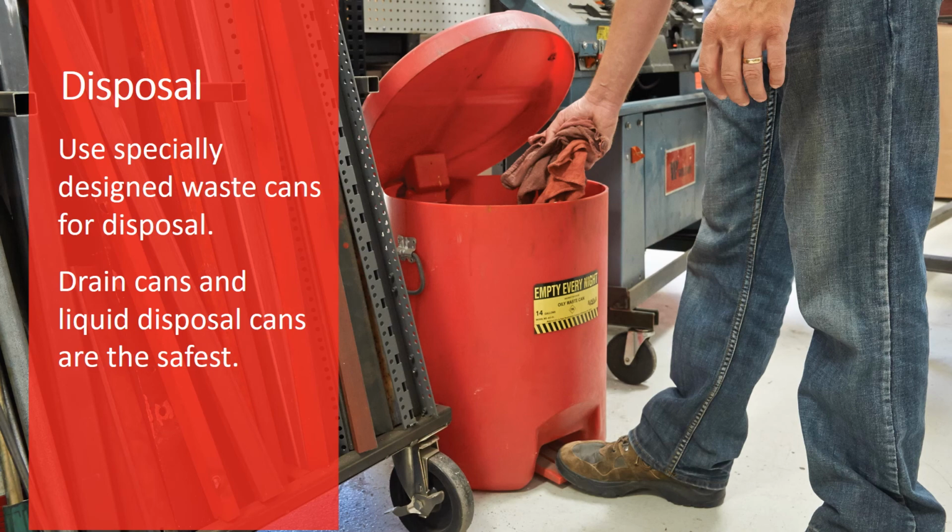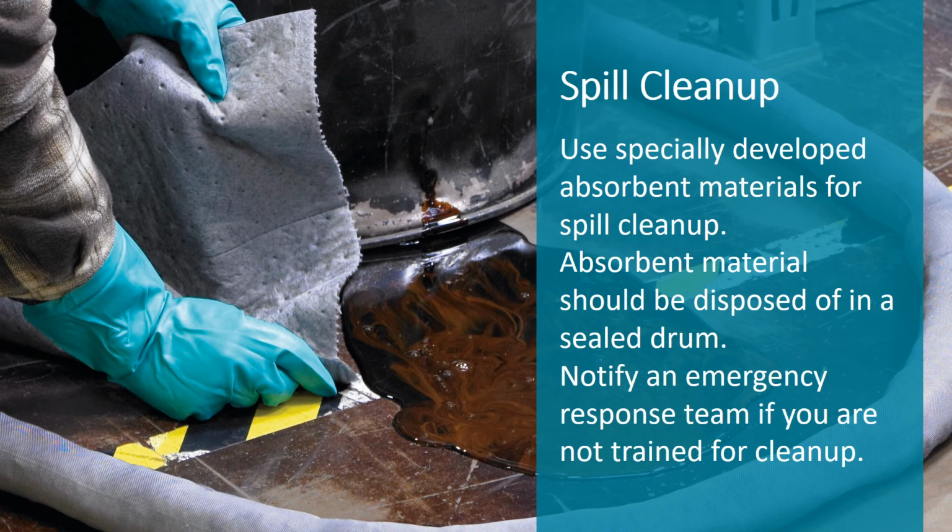For removing flammable liquids from the workstation for disposal, drain cans and liquid disposal cans offer the greatest degree of safety. It is the vapors rather than the liquid itself that burn. When the liquid is spilled, vapor release begins immediately and continues until the liquid is removed.